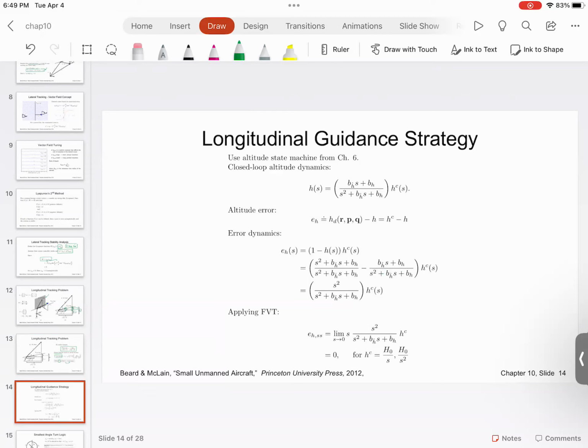At the end of the day, whether you like it or not, this is going to be a simple equation that involves some type of PID control or second order control. For this, you add some if-else type of conditions, and you can either write if-else conditions or use state flow machines. So you use the state flow machine.